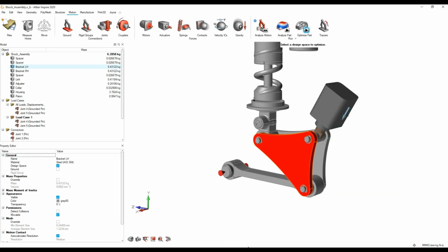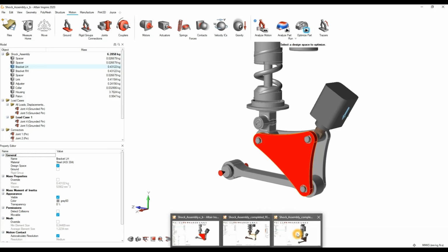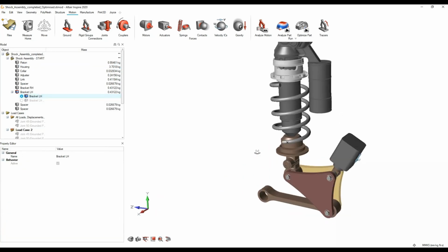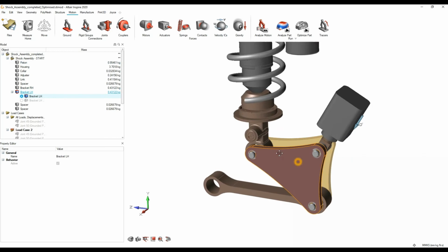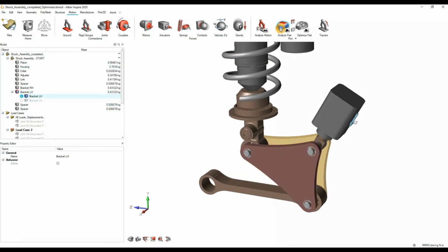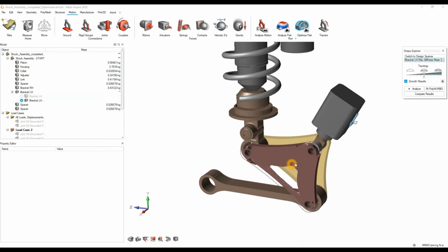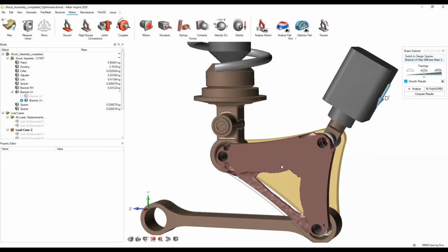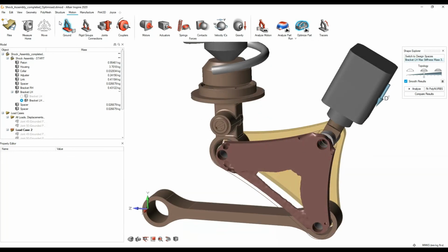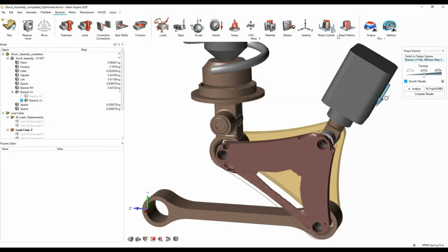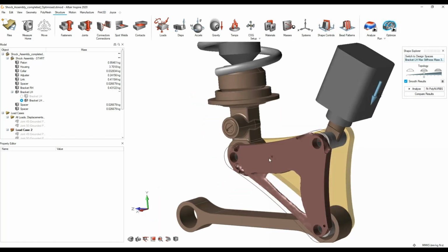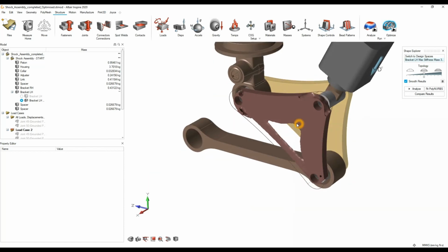Now I already have one that ran, so it only takes around 20 minutes to run, but I've had one that's already run. So you can see it's the same setup again, and in this case once it's finished running, just by clicking on the truss button at the top here, you can see that this now gives you a new design. So obviously if you head back into structure, you can specify other manufacturing constraints to it as well, if you want to specify symmetry or draw direction, etc. But the Inspire structural analysis video should take you through that instead.